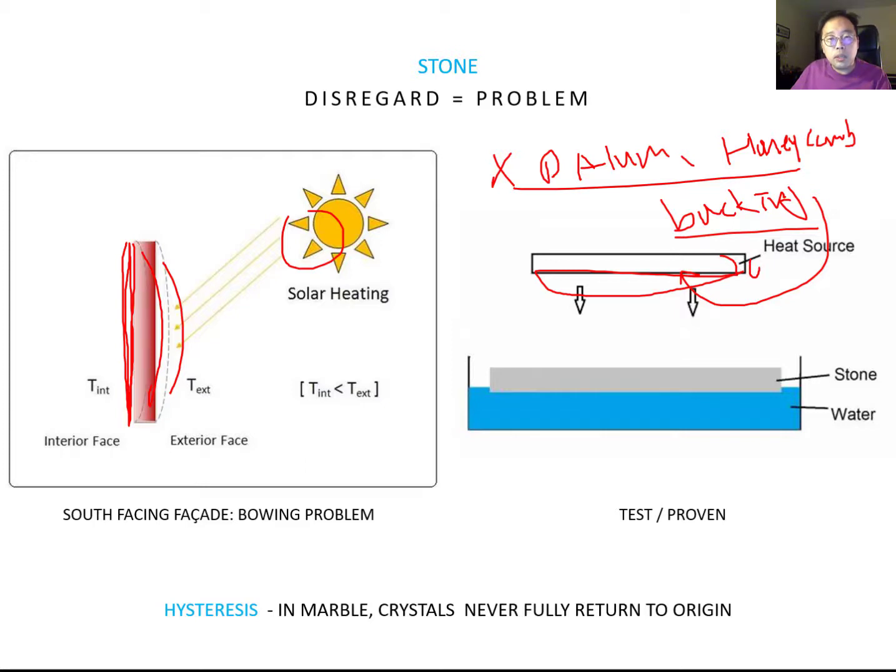The next one is that manufacturers keep testing, a bowing test, 40 times to 200 times, and we only use products that pass the bowing test. So nowadays the marble panel is not bowing too much, but still, if you get the cheaper one, you can probably find these bowing issues.